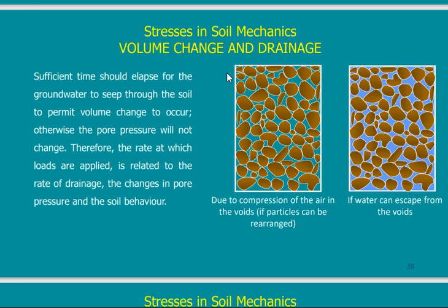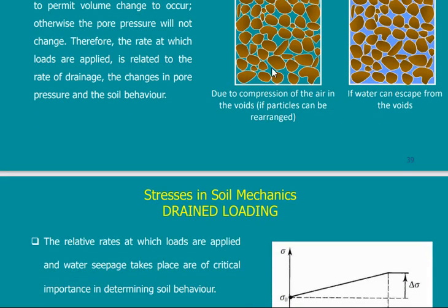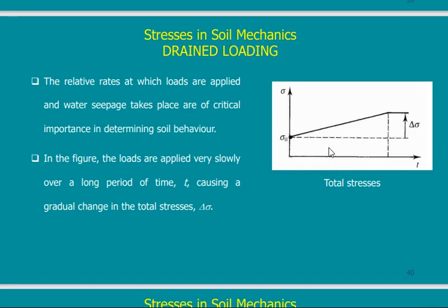on sand and a building standing on clay. The building standing on sand, once the load is applied, the sand will settle and that's it. But the building on top of the clay, like in some places in Alexandria, you find that the building, maybe after a year, is still sinking in the ground. How is this happening? Because it is still expelling water, and once it expels the water, the voids diminish and settlement happens. So this is just an introduction to water in the soil, but these charts are very important.